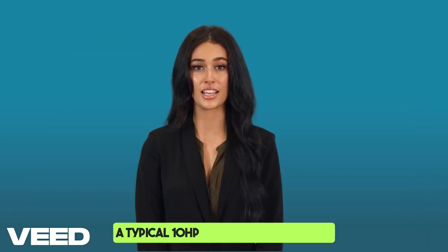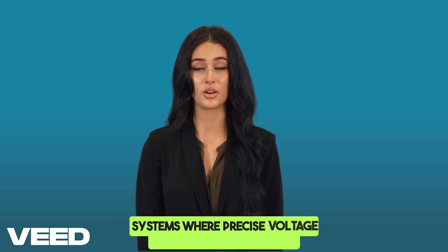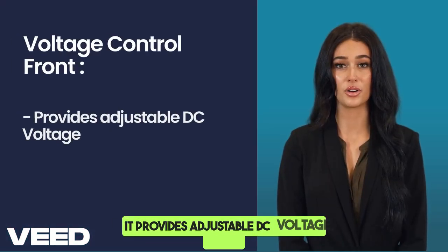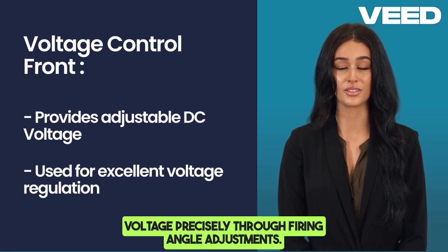A typical 10 HP fan motor running at full speed doesn't require variable DC voltage. It can be used on simple conveyor systems where precise voltage regulation isn't critical. So, an uncontrolled rectifier VFD is a great low-cost option. While a controlled VFD provides adjustable DC voltage, which is required to control output DC voltage precisely through firing angle adjustments.